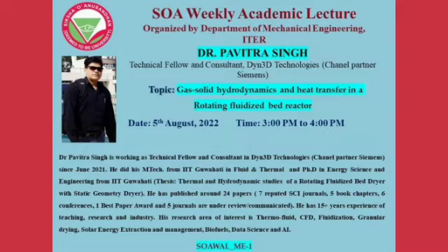dm/dt is equal to minus K A (Mg minus Me), where Me is the equilibrium moisture content and Mg is the moisture content of the grain. K is a constant, A is the surface area. So this drying process actually completes in two regimes. First is the constant rate period A to B, and second is the falling rate period B to C. So I would like to talk about the constant rate period A to B.